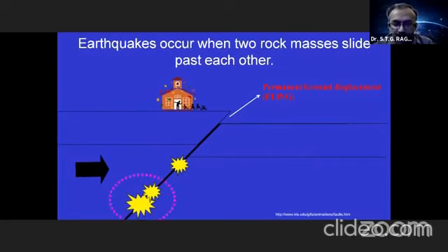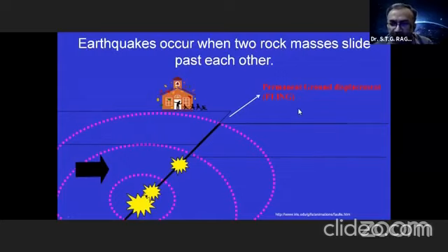This is how the waves start propagating. The most important thing in why earthquakes are dangerous is this rupture speed. If things were moving very slowly, say 1 meter per second, then there would be no need to worry about earthquakes at all, because you would not have any vibration, and it would have been fine. The whole danger of earthquakes arises only due to the speed. So speed kills in earthquakes also. This is how the waves propagate and the ground starts vibrating. Please all of you note down this most important thing, the fling, which is what we call the permanent ground residual displacement at the end of the earthquake.